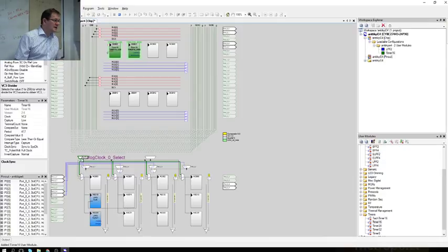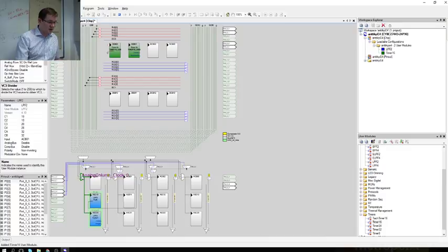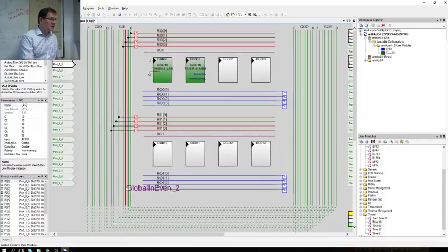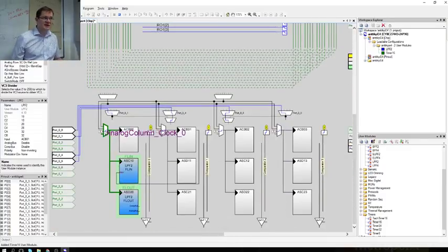So that's basically the column clock we need to check. And that column clock comes from this multiplexer. Maybe I should show it better. It's this multiplexer which is used for that 480 hertz signal, and we can go VC1, VC2, or either of the multiplexers.